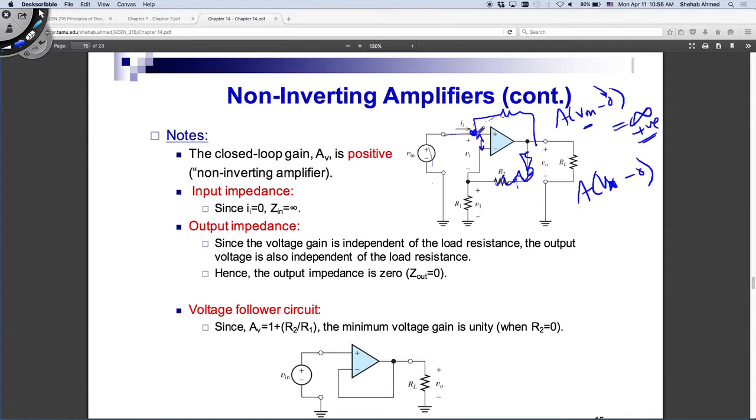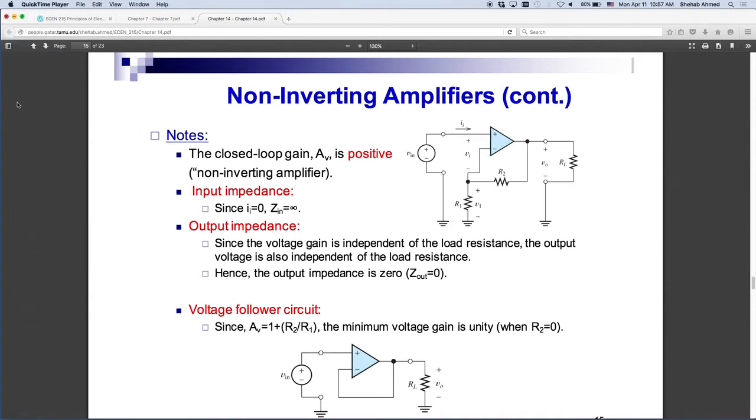So I cannot put a feedback resistor here, right? If I want to put a feedback resistor, I'm putting it where it will drive this Vx, the differential input voltage, to 0. So how can I drive this differential input voltage to 0? I look at the sign of the differential input voltage. The sign of the differential input voltage here is positive. It's this terminal's voltage minus this terminal's voltage. Before, it was negative.